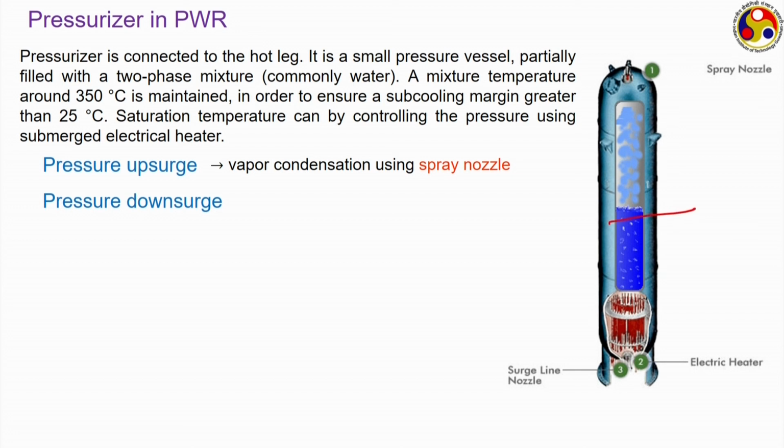So, now a larger volume is available for the vapor phase, and hence the pressure on the liquid surface also reduces, and because of that some liquid from this portion, as both liquid and vapor part are already at the saturation temperature, will flash into vapor and occupy this portion, thereby contributing more molecules to the vapor part. That increases the pressure in the vapor part, and hence is able to attain the equilibrium, or the entire system can go back to its original position.